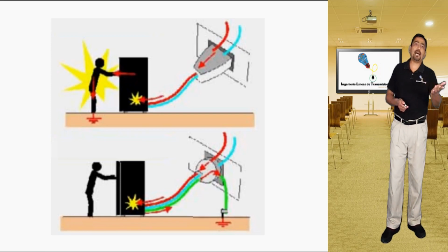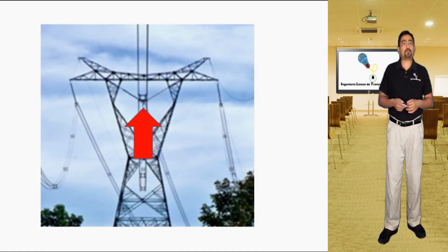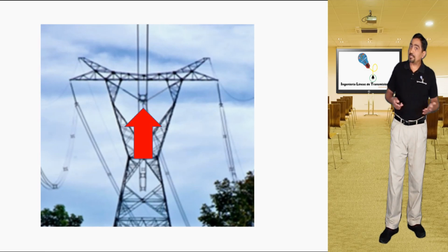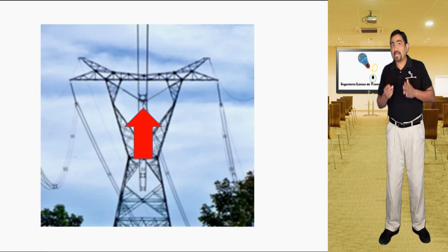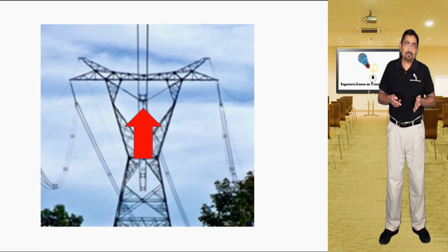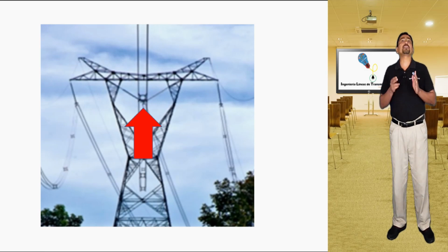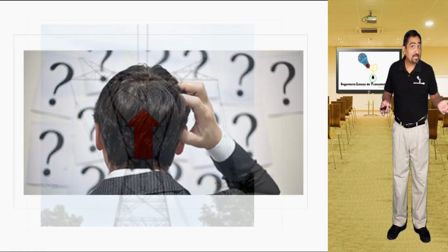Or how about if you have structures with V's of suspension assemblies, and a customer concerned about the safety of their hardware assemblies requests a calculation to guarantee that these assemblies will not get into compression at any given moment and might fail? Let's remember that insulators are elements designed to work in tension, but not in compression for a long time. So, how do you make that calculation?